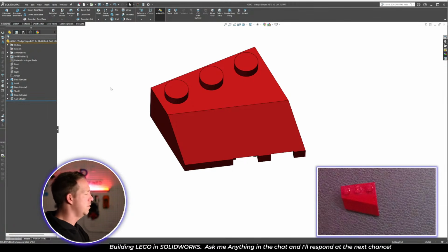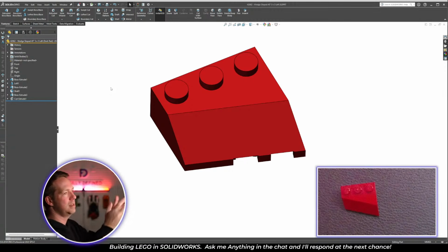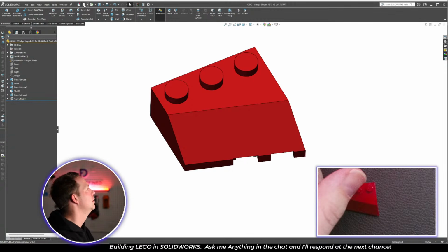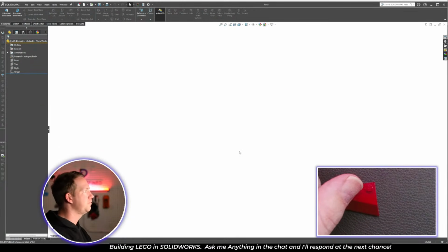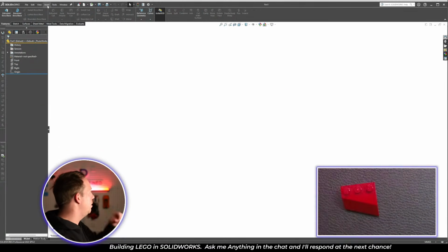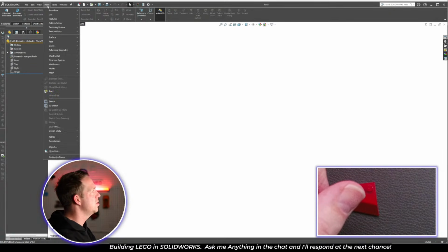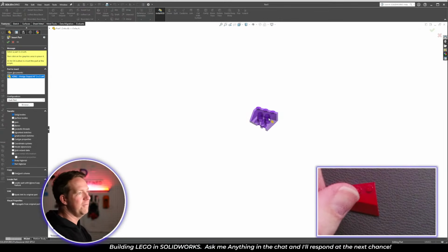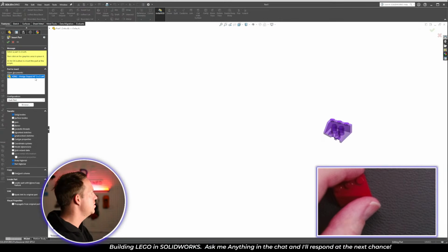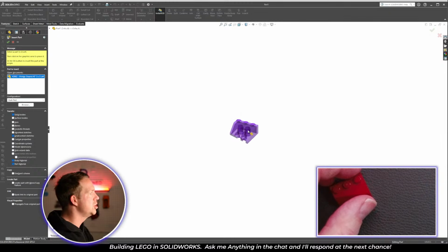So the way you do it, the top-down assembly, you create your master file like what we have here, and then I start a new part file. So this would be intended as my child part. And then I use insert part as a feature, basically, and I'm going to insert the wedge.